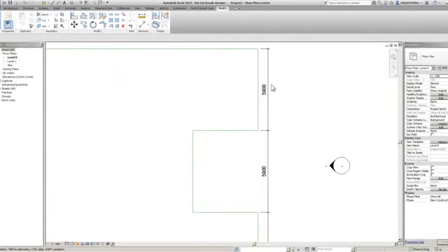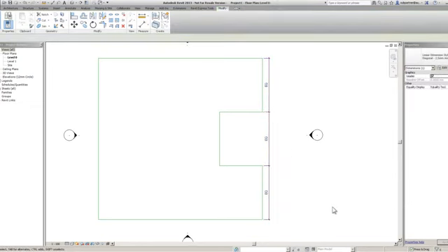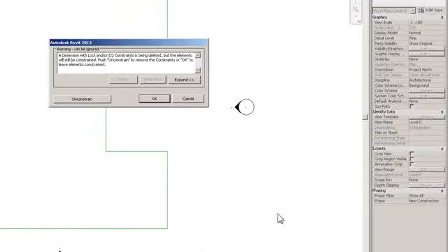And as you can see, they're all 5,900. Watch this. What I tend to do is highlight it, put the equals constraint on it, and then delete it. Once you delete it, this little box will appear, basically saying, whoa, hang on a minute. It's giving you a warning that what you're doing is trying to remove a dimension with a constraint on it. Are you sure you want to do that? Obviously, you can cancel out of it. You can press unconstrain, and it will remove the dimension and remove the constraint.